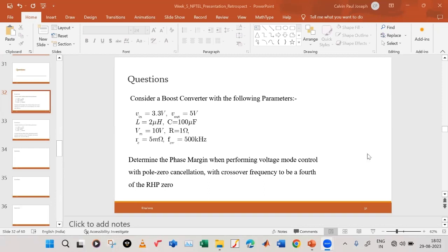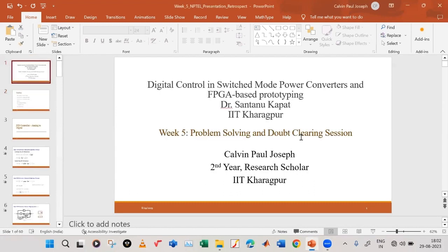If you're trying to produce the ramp using a current source and a capacitor, how do you suddenly reduce IC by C to 0? Because the dVc by dt, if you charge a capacitor using a current source, then with IC by C we can get the slope dVc by dt. Yes, it's correct.